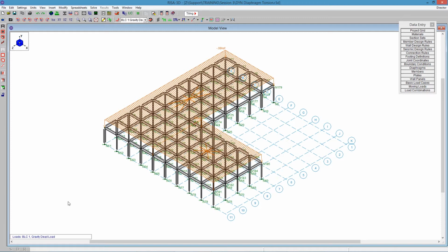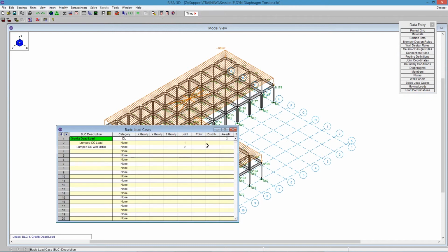Additionally, you can do your storage live load. That's required here. It says in the ASCE 7 you have to do 25% of the floor live load needs to be included in the seismic mass for the storage live loads. Also permanent partitions, you need to account for actual loads if you have permanent partitions in there. Also snow load. So in regions where you have higher snow load, you want to open up the ASCE 7 and take a look. It's going to be typically 20% of the uniform snow loads in certain regions. So you want to make sure you have that dialed in. It's also all for your seismic weight.